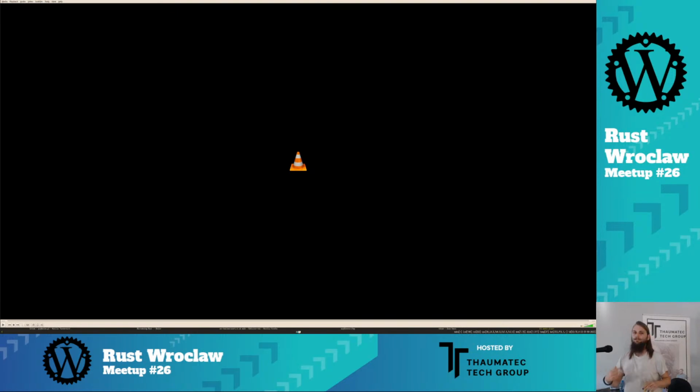You have only 32 kilobytes on the AVR, and the problem is, the whole video, if you just download it from YouTube with the whole resolution and stuff, would take probably 100 megabytes or so. And then you have this AVR with 32 kilobytes, and you have to store that. I mean, you don't have to, because no one forces you with a gun, but if you want to, you can. First you have to take some place for the encoder itself, because you have 32 kilobytes both for the data and for the video itself. So there is this trade-off between how good an encoder you can make and how much space it takes.